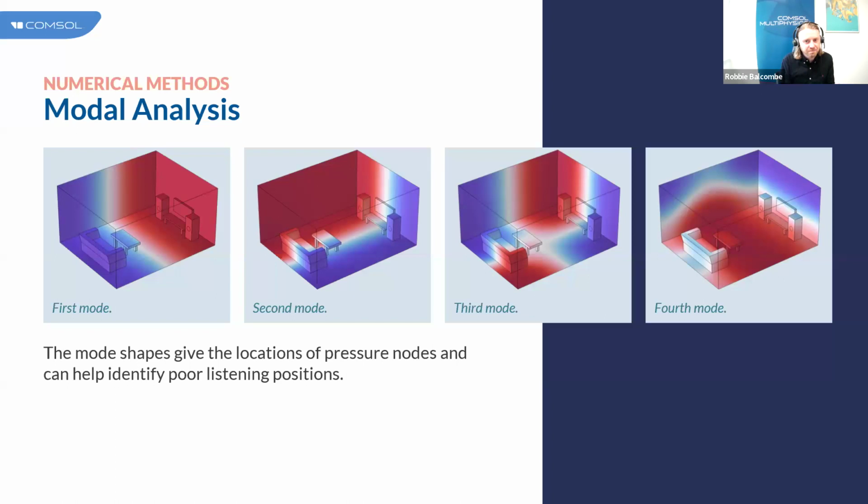Now, DGFEM bypasses this. It doesn't rely on generating a large stiffness matrix, and therefore it doesn't need to invert one. So it removes the costly step from the solution process, and that's why it uses fewer computational resources. So there's no stiffness matrix that's generated.